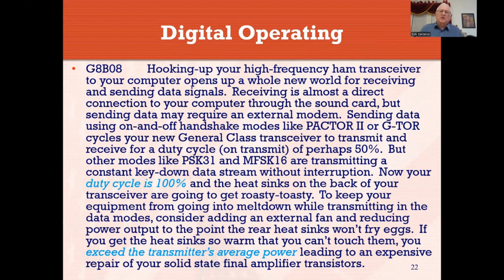Okay, hooking up your HF transceiver opens a new world. Yeah, we've said that. Receiving is almost a direct connection to your computer through the sound card. It's not direct, but almost direct. Sending data can require an external modem, such as the PACTOR. PACTOR is a special format, and it does require a special modem to handle its signals. Sending data using on-off handshake modes like PACTOR 2 or GTOR, which again are just two of the modes of sending it, does require a special modem, as we said.